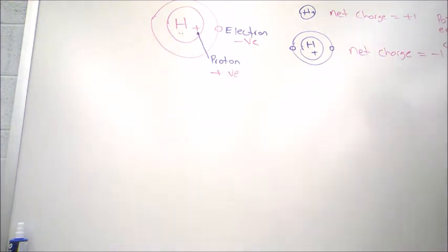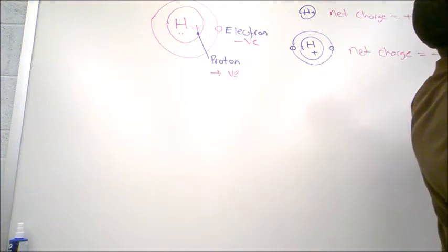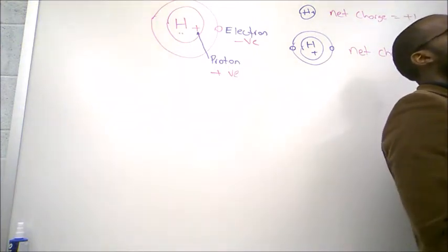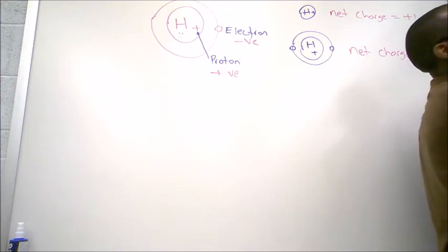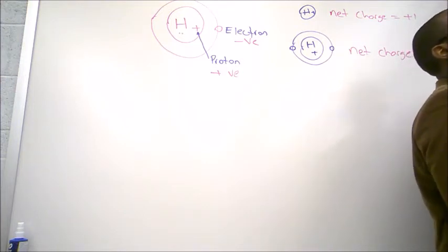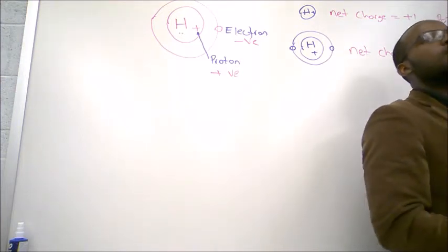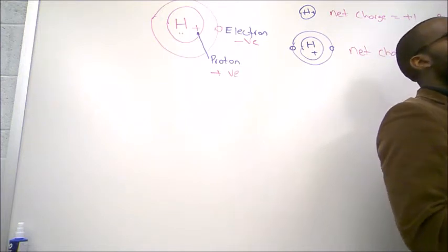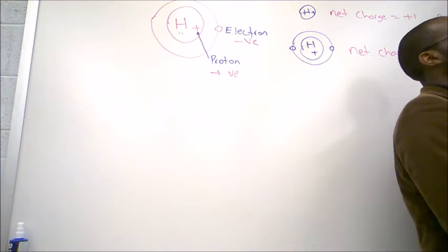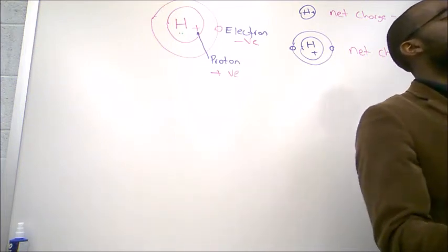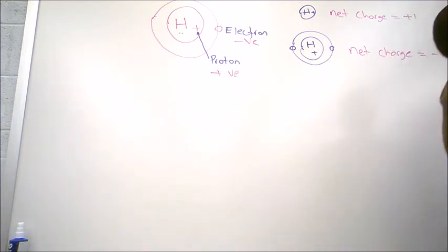Okay? Now here we have a piece of wire. I'll just list some materials that we use for conductors. Most times they're going to be copper or silver or aluminum. Iron you will get, but iron has very high resistance, and we're going to talk about resistance in a second. So again, the most popular materials we use for conductors, like all these wires you see here, inside of them, most times we have copper.